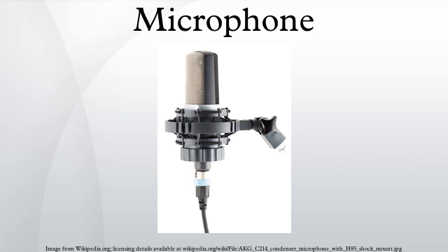60268-4. A frequency response diagram plots the microphone sensitivity in decibels over a range of frequencies, generally for perfectly on-axis sound. Frequency response may be less informatively stated textually like so: 30 Hz to 16 kHz plus or minus 3 decibels. This is interpreted as meaning a nearly flat, linear plot between the stated frequencies, with variations in amplitude of no more than plus or minus 3 decibels.